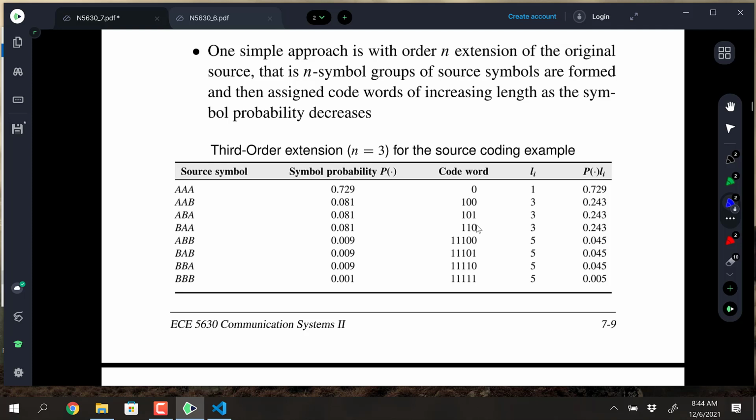The problem I'm thinking of is problem 12.11, and it gives you an exponential PDF, and it says the signal is to be quantized using 4 quantization levels. Your job is to set those quantization levels, but the idea is to maximize the entropy of the quantized amplitudes. So you're playing around with that to get equally likely probabilities in each of the quantization levels with the exponential PDF. It's not exactly this problem, but it is thinking about entropy.